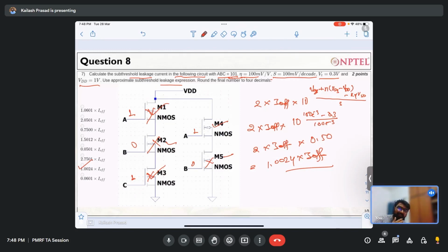The second is the leakage current, right? That is what we call the subthreshold current, right? And the leakage is actually of three types. We have seen it can be the gate drain leakage, it can be the gate dielectric leakage, and the most important component is the subthreshold leakage, right?